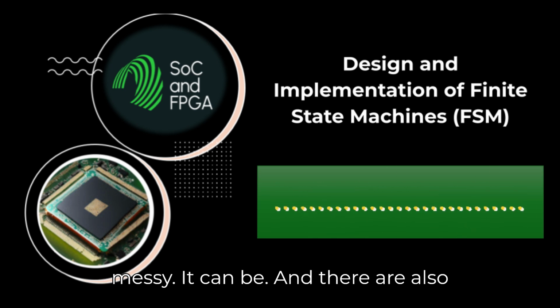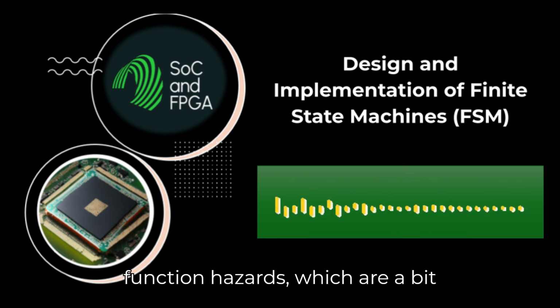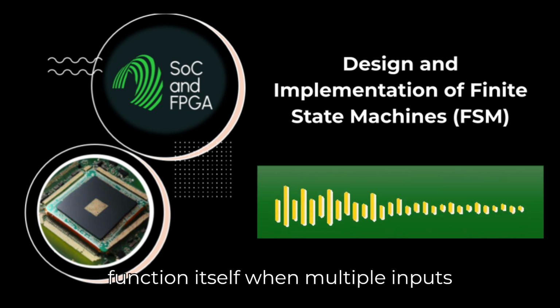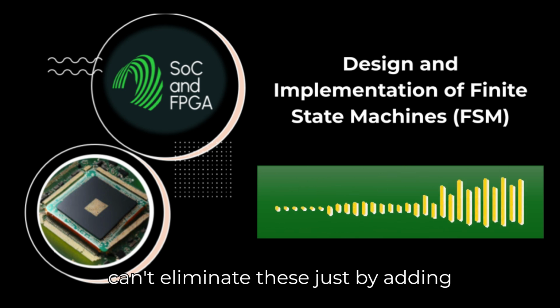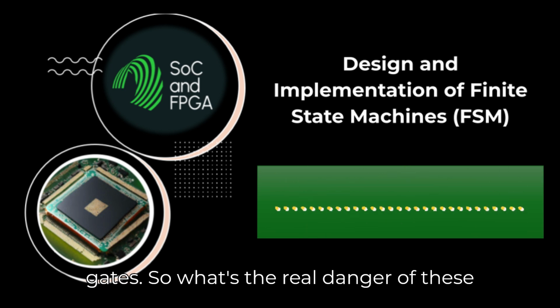It can be. And there are also function hazards, which are a bit different. They're inherent to the logic function itself when multiple inputs change simultaneously. You sometimes can't eliminate these just by adding gates. So what's the real danger of these glitches?